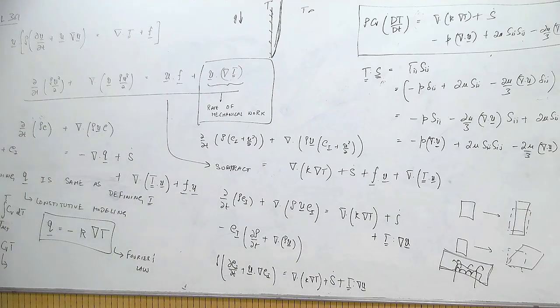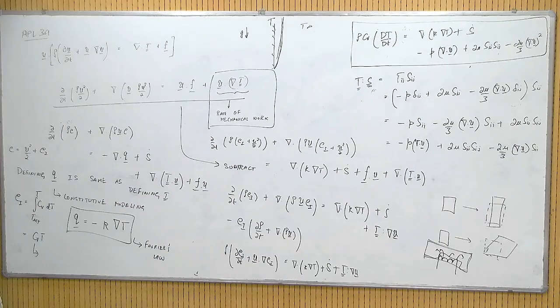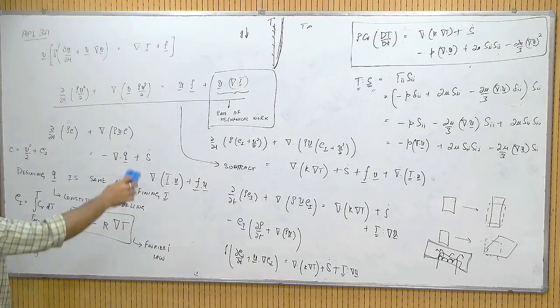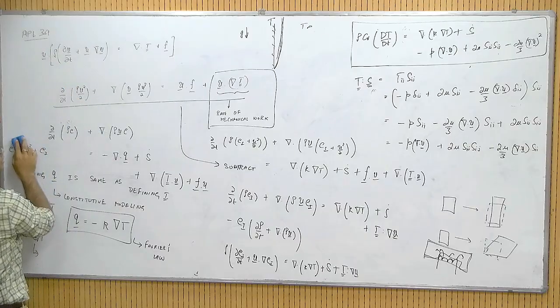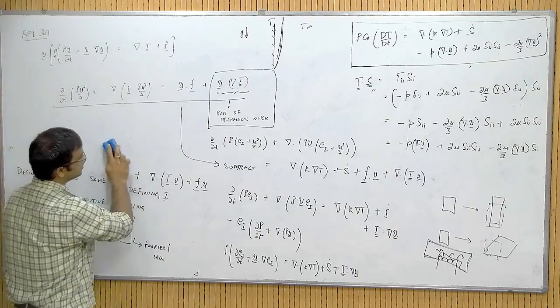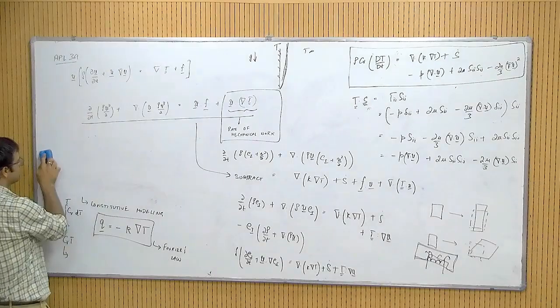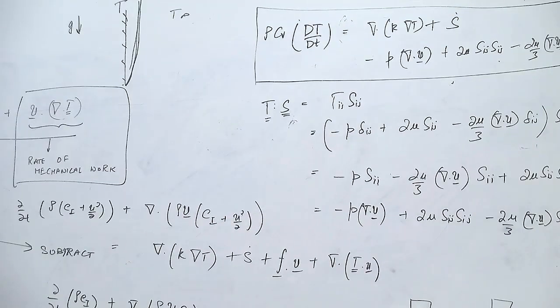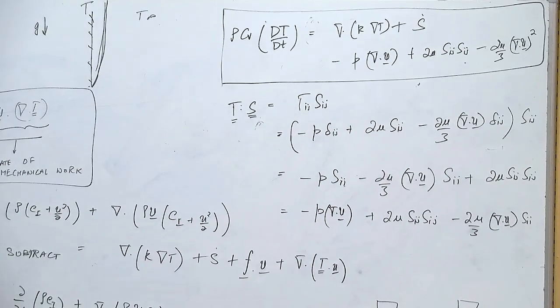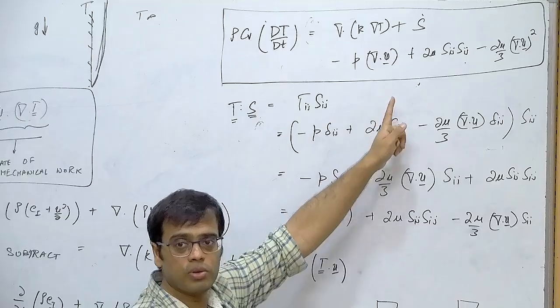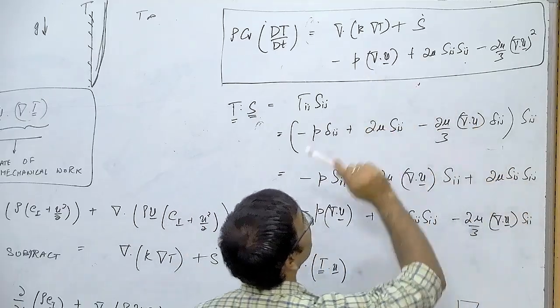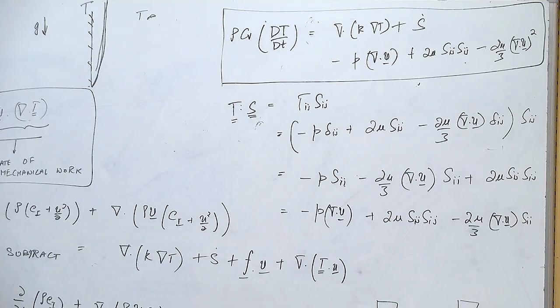So if there are no questions, then we can move forward with our discussion specific to incompressible flows, because this course is mostly about incompressible flows. You can simplify this equation for incompressible flows easily, right? This term will go away, this term will go away. Wherever del dot U appears, you can substitute it to be 0 and those terms will go away.